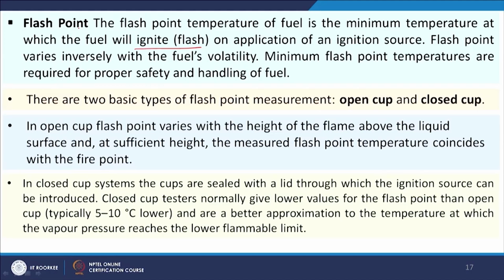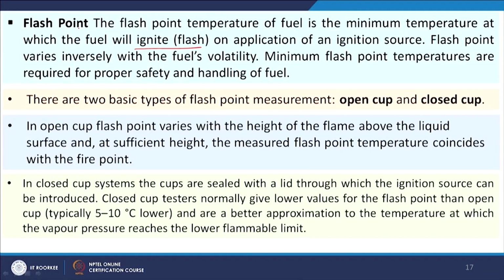If we heat any fuel, it will produce vapors. If we bring a matchstick or an ignition source, at some temperature sufficient vapor will form and a flash will take place for the first time. That temperature is called the flash point. If we apply more heat, the temperature will increase and more vapors will form and fire will take place; the minimum temperature at which fire takes place is called the fire point.